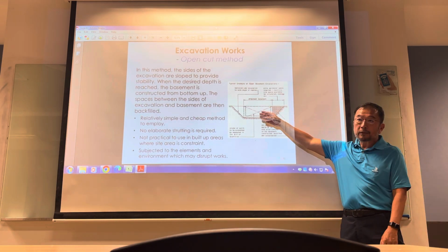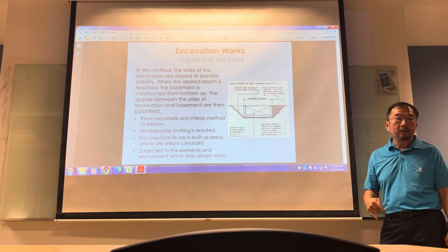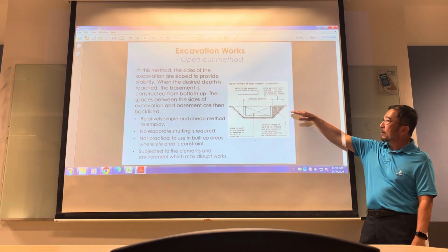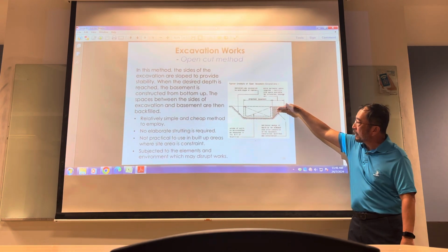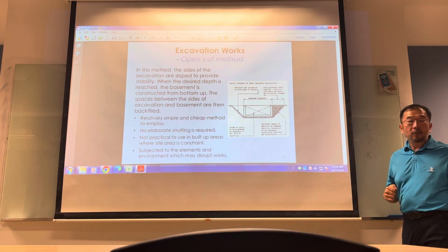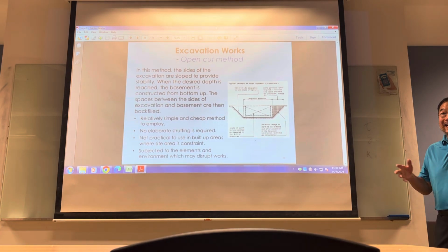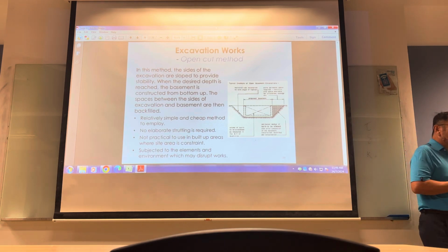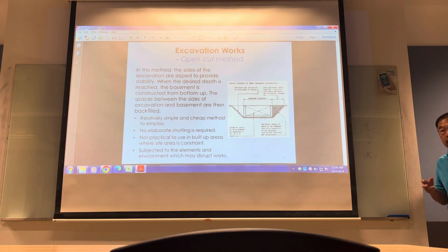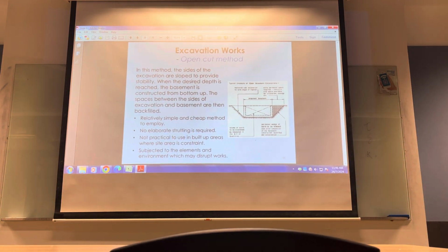If your soil is soft, there's no way you can do open cut, because as soon as you cut, the soil from top falls down into your excavation. When you hit water table and you cut below the water table, water come into your excavation. You'll be busy pumping out water. Pumping out water in Singapore is only one part of the solution. Second part of the solution is to clean the water before you discharge into the drain. If you discharge the drain dirty water, again, Singapore being fine city, you will get fined. So a lot of consideration before you choose the method of excavation.